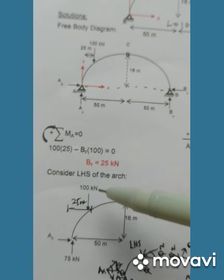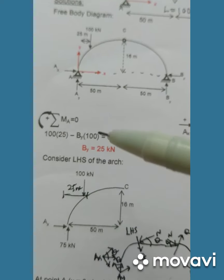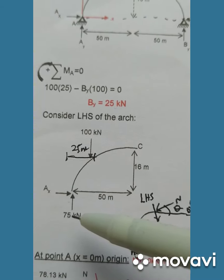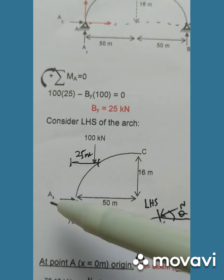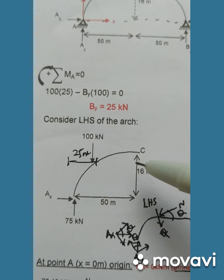So I consider the left hand side with the 25 meter here. I put the AY that I got previously, AY equal to 75 kilonewton. So taking moment at C, 75 times 50 minus AX times 16 minus 100 times 25.